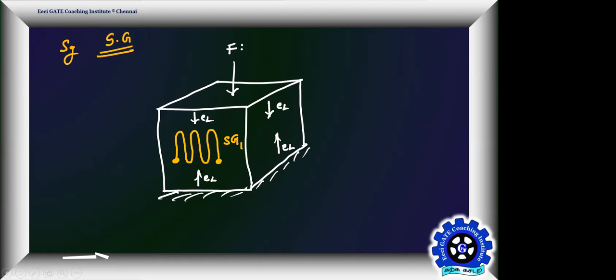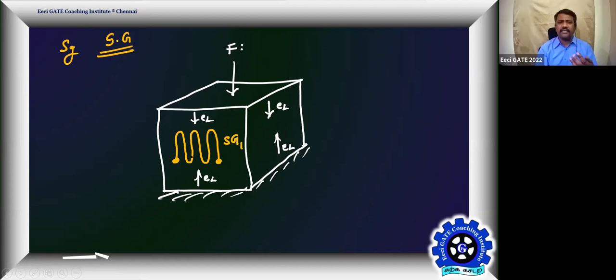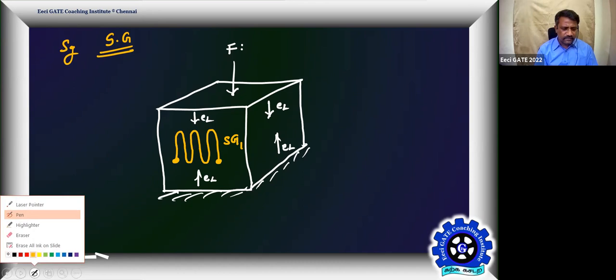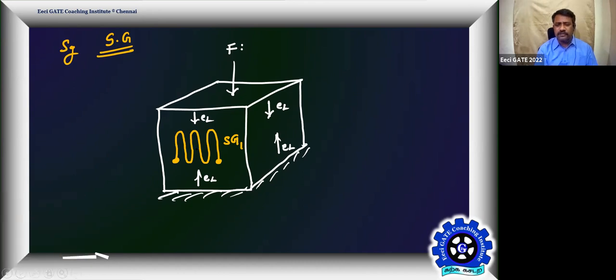Yes, sir. A strain gauge is nothing but a metal wire, pasted like this on the surface. Tell me what is going to happen to this wire. The surface of this load cell is experiencing strain, so here EL is acting, here EL is acting, and here EL is acting. Agree, everyone? Yes or no?